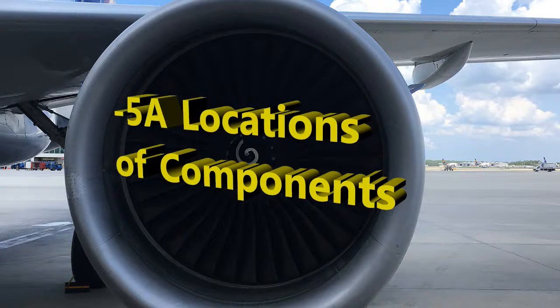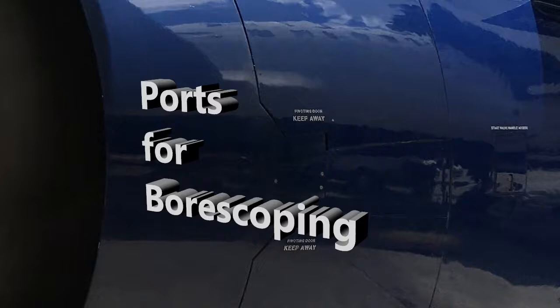All right. Now you have ports for bore scoping, because there are some areas where it's not visible to the eye from an ordinary position of maintaining or working on them. For the high pressure compressor section, this is where you have the bore scope ports. There are 9 of them, approximately at the 5 o'clock position, and they're numbered. Again, just follow the manual. I'm not going to name them because I don't want to confuse you. Just know there's 9 bore scope ports, and those are on the lower stator case.